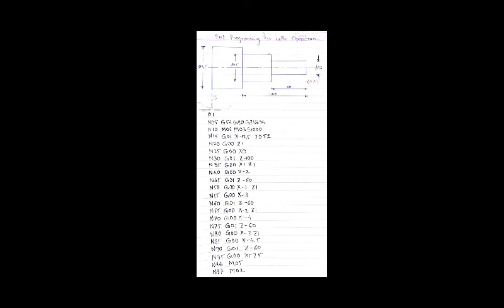So here the axes are a little bit changed, as we have seen in previous videos, that was for milling and drilling. Okay, while in milling part programming we were using the end mill cutter, and our cutter's position was vertical. So in that condition the Z axis was vertical, the spindle axis was the Z axis, the horizontal axis was the X axis, and the vertical was the Y axis. That was in milling, and the same for drilling also. In drilling we were using a vertical drill bit. So that was the Z axis, and in the workpiece, its horizontal axis was the X axis and its vertical axis was the Y axis.